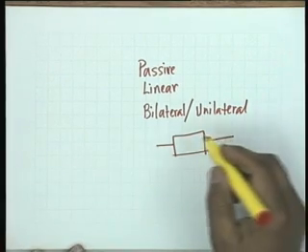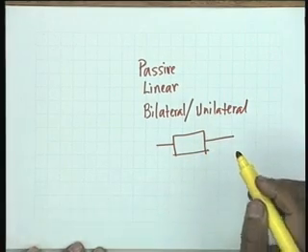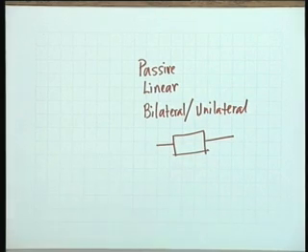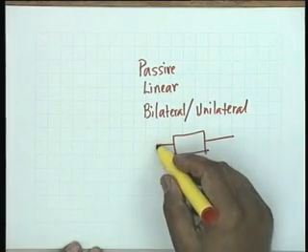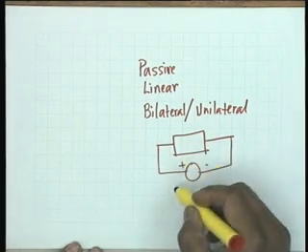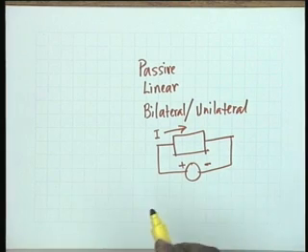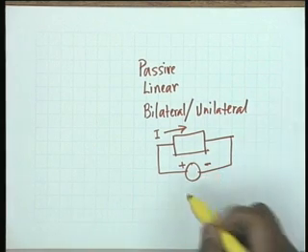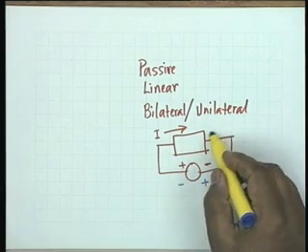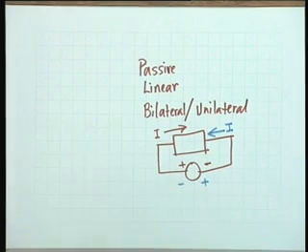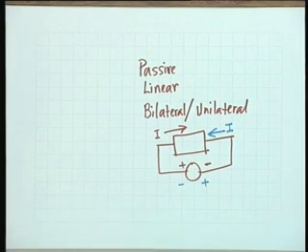All right. Now a two-terminal element is called bilateral if it can pass current equally well in both directions. That is, if you connect a voltage source here with this polarity, current passes like this, and let this current be capital I. Then if you interchange the polarities, let us say this is minus and this is plus, then the current will pass in the other direction and the same current should pass. Then it is called a bilateral element. The term bilateral refers to a two-terminal element.